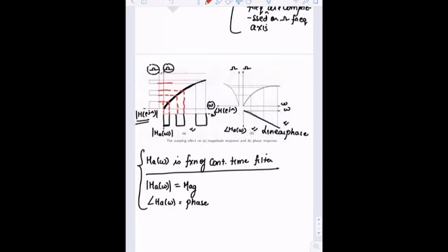Now if we say that the width of these frequencies on the continuous frequency axis is the same, the width on the discrete frequency axis will keep decreasing as the value of continuous frequency omega increases. So we can see that the width decreases. This is because of the frequency warping. Very simple to understand.